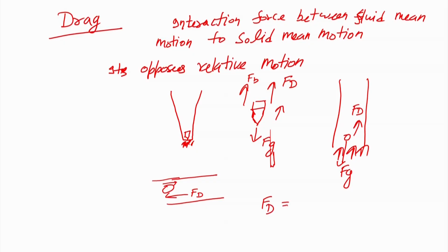So, that is the way this force is being defined, and Fd is being defined very close to the way friction, or frictional force, has been defined. So, the friction force, tau w, is being defined as the frictional force divided by the area, that was being defined as rho V square upon 2 multiplied by f.